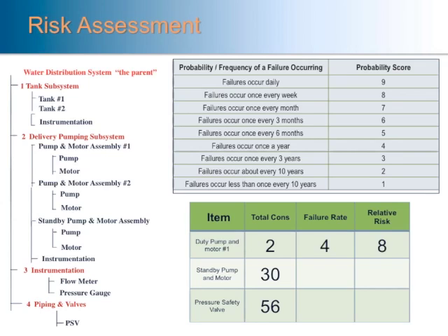The operator is directly linked with that equipment and says, typically we've had issues with that equipment about once a year. So we would end up with a failure ranking of 4, and the product of those is a relative risk of 8. Ask the same question for the standby pump, and we find that this particular pump is actually quite unreliable. Standby equipment tends to be ignored. Standby equipment is also a wonderful parts source. I can't tell you how many times I've heard stories of people going to start a pump and motor, and the motor is missing. It was a wonderful replacement for something else.